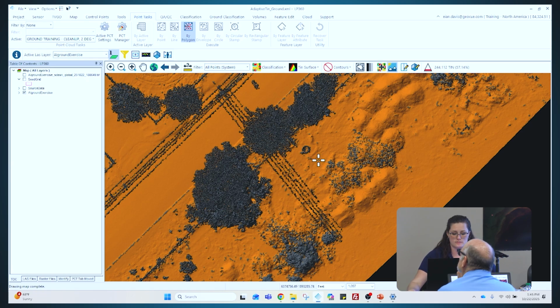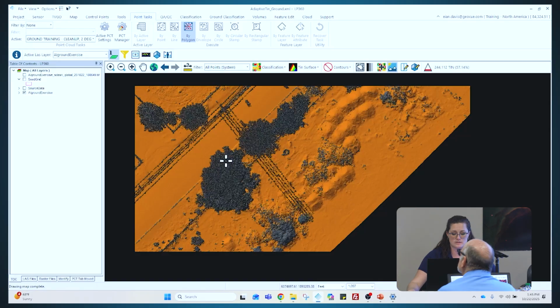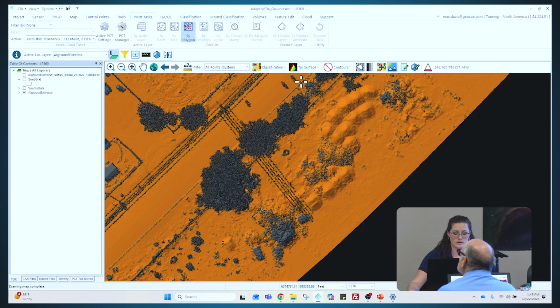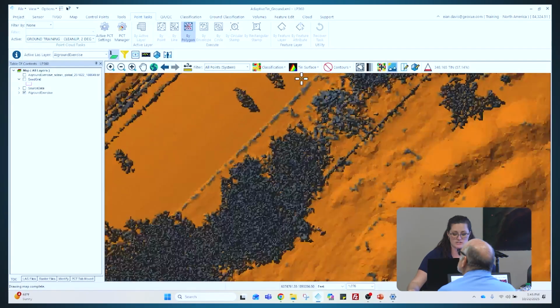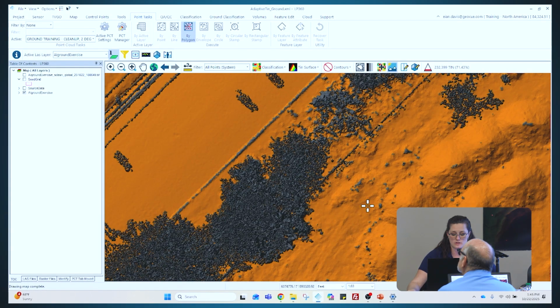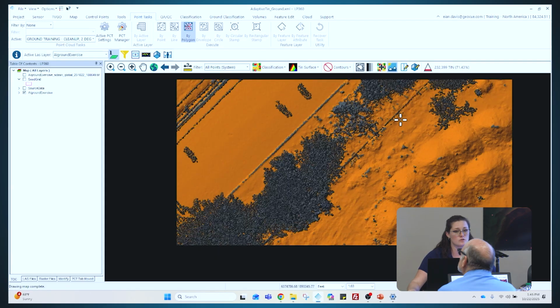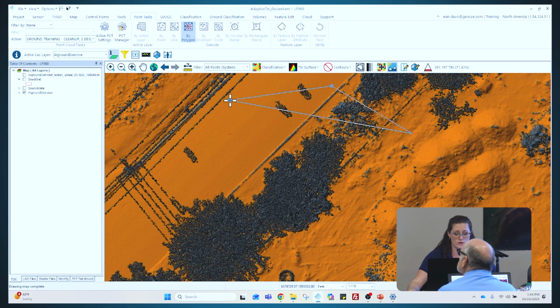All right. The same thing can be done outside of the profile view, so you don't need it. But I could do the exact same thing, just drawing around here, because I can see there's many spots it missed for my curb. Double click. Again, it is still going to wait for me to select some points. But when I am using this particular view, it can be a little more difficult to identify only ground points.